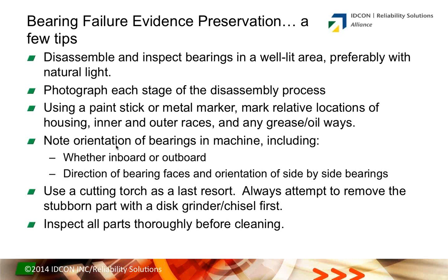One thing is, if we're disassembling bearings, let's have an area to do it. Let's have a nice area, preferably natural light, but a well-lit area. We don't really want to use sodium lights or incandescents because they put an orange hue on everything, and sometimes we're looking for those colors to tell us what's wrong.